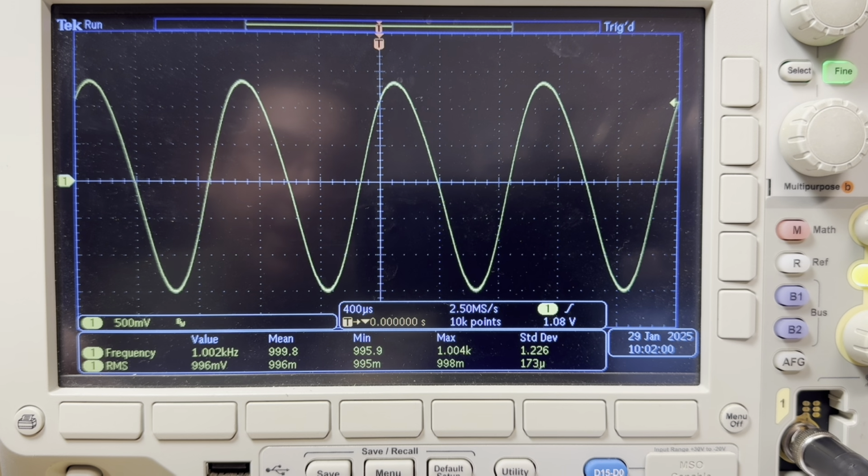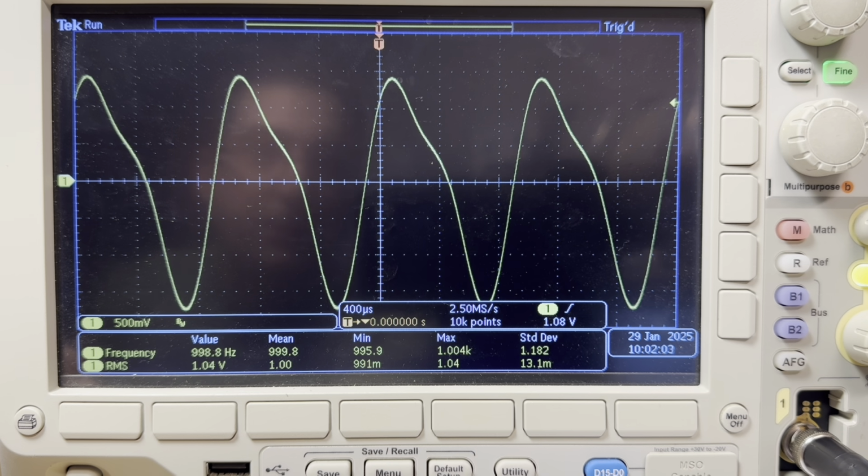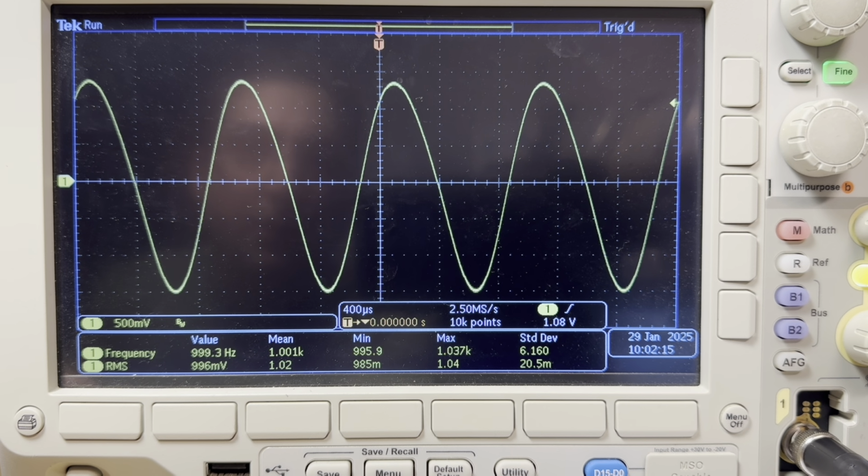I can back the distortion out, so now we're at minus 10 dB, so this would be equivalent to a 30% distortion level, and you can see now the sine wave is greatly distorted. Now, to the trained eye, some can claim that they can see on an oscilloscope distortion levels at 1% or even 0.5%. So let's see if we can see the difference.